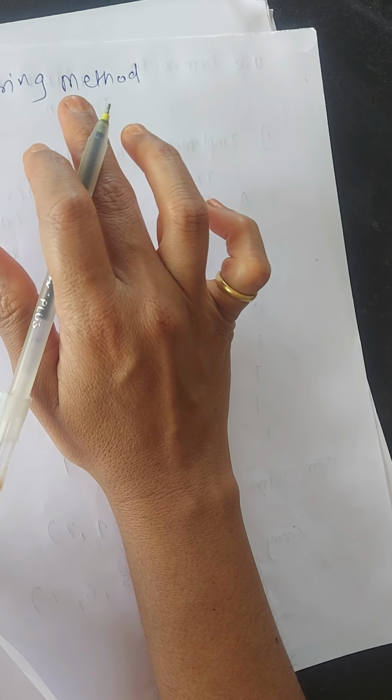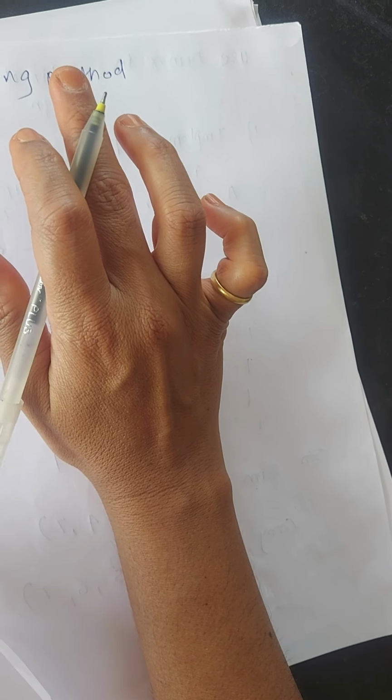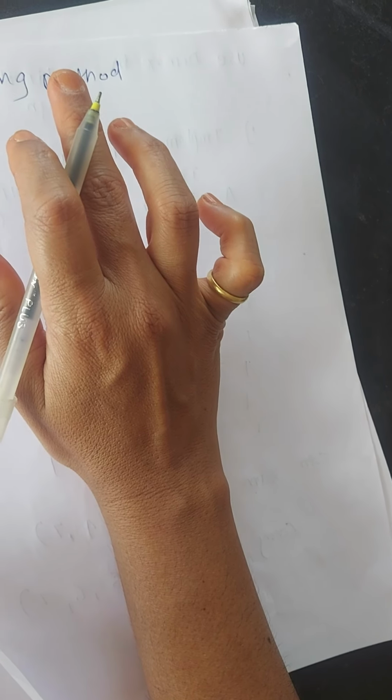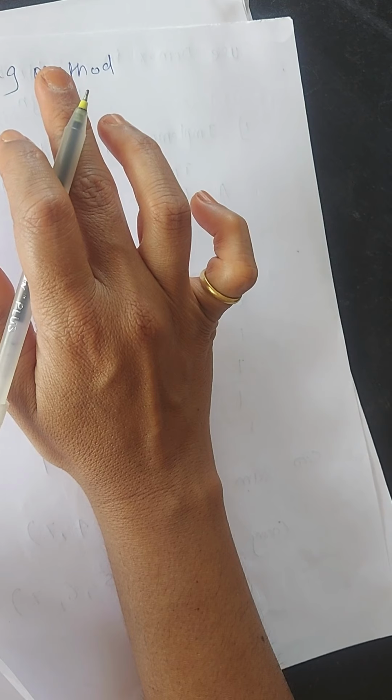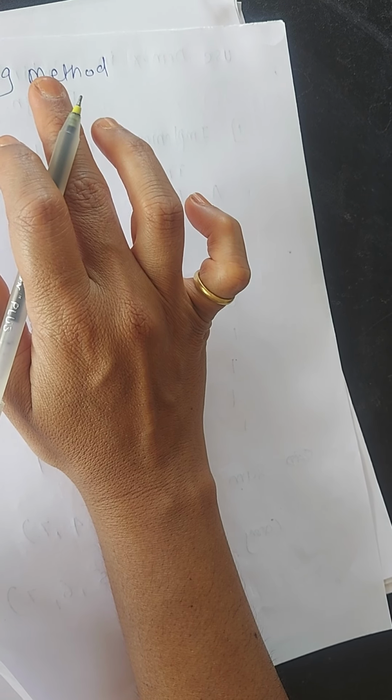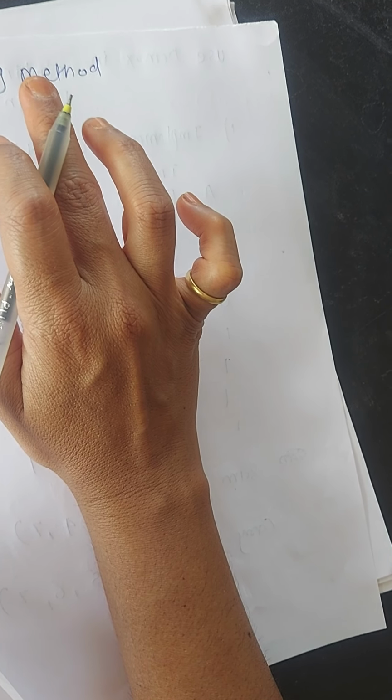Difference between latch and flip-flop: latch and flip-flop both are basically bistable elements, and a latch has an enable input, and as long as it is active, the latch output will keep changing according to the change of its input. In other words, a latch is a level triggered element, but a flip-flop is a sequential circuit which samples the inputs and changes the outputs only at a particular instant of time, not continuously.